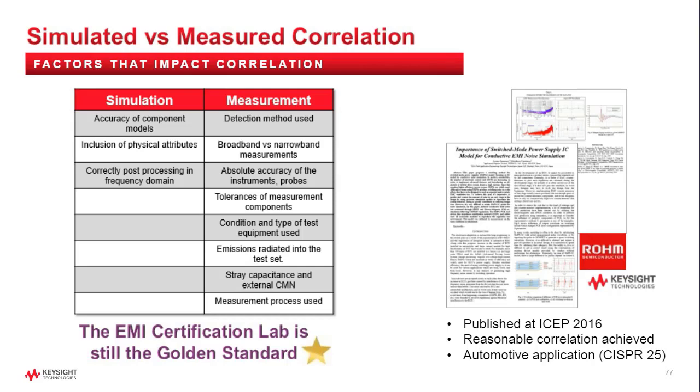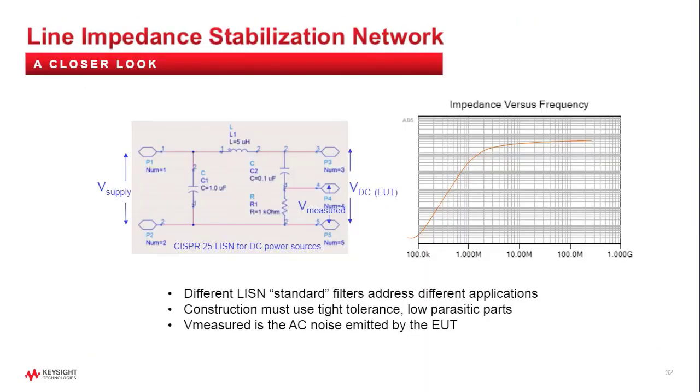On slide 32, the circuit looks like a low-pass filter rather than a high-pass filter. Usually there's a capacitor blocking DC when it's a high-pass. Do you have any comment on that? You want to go back to slide 32, if you can? They said the circuit looks like a low-pass filter instead of a high-pass. The question is, usually there's a cap blocking DC when it's a high-pass. Do you have any comment on this?